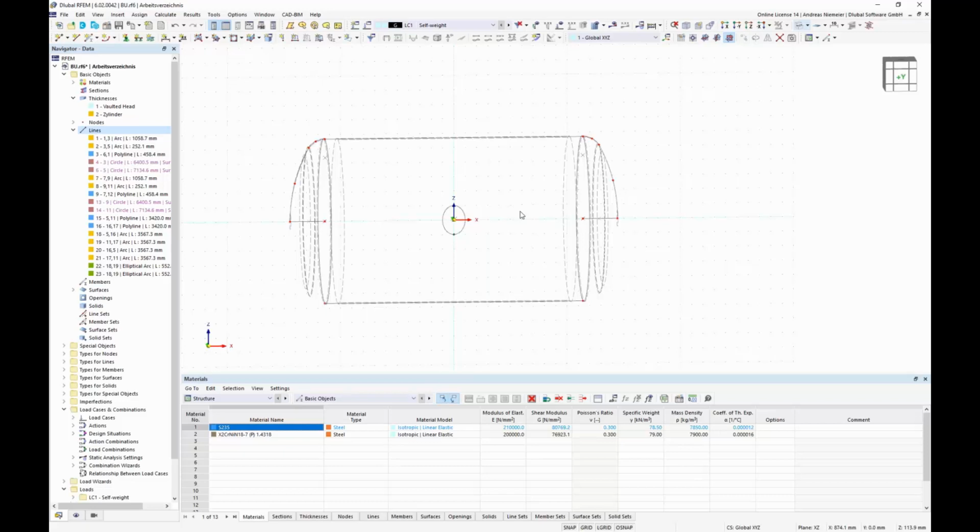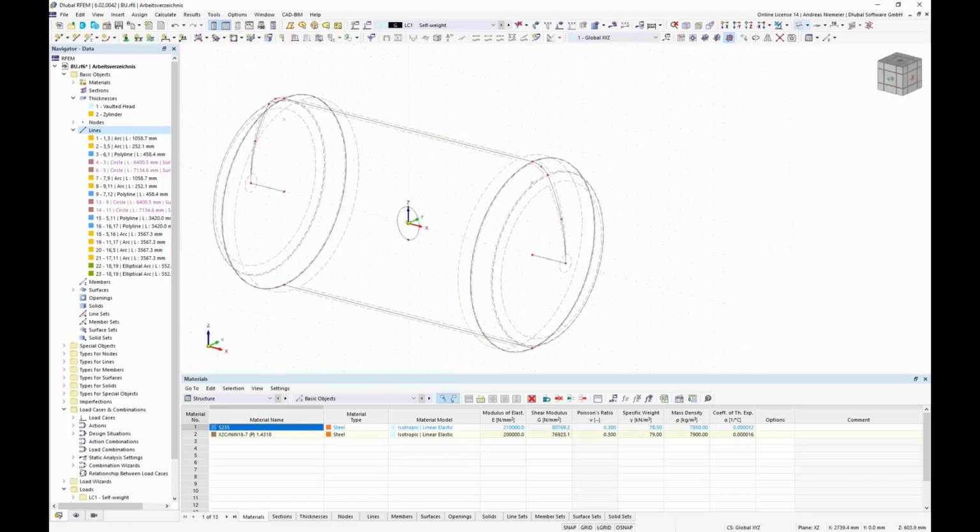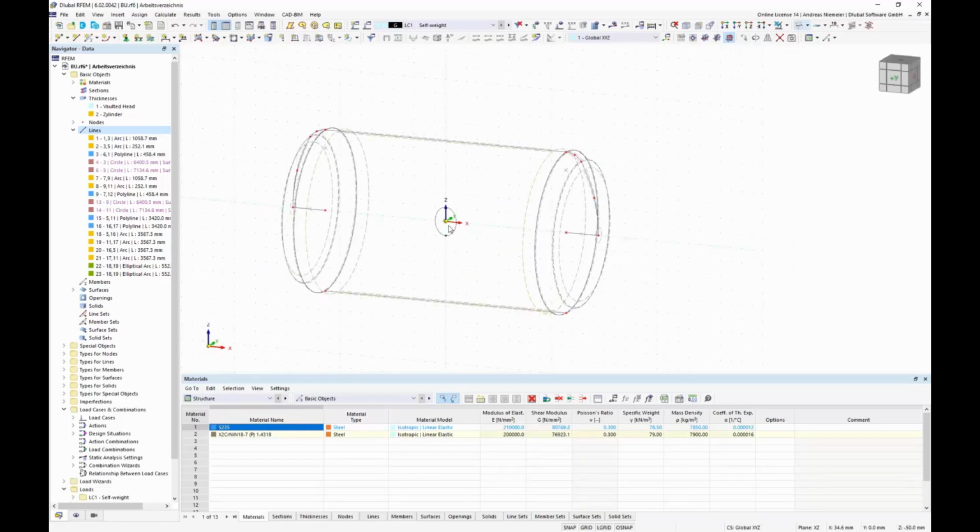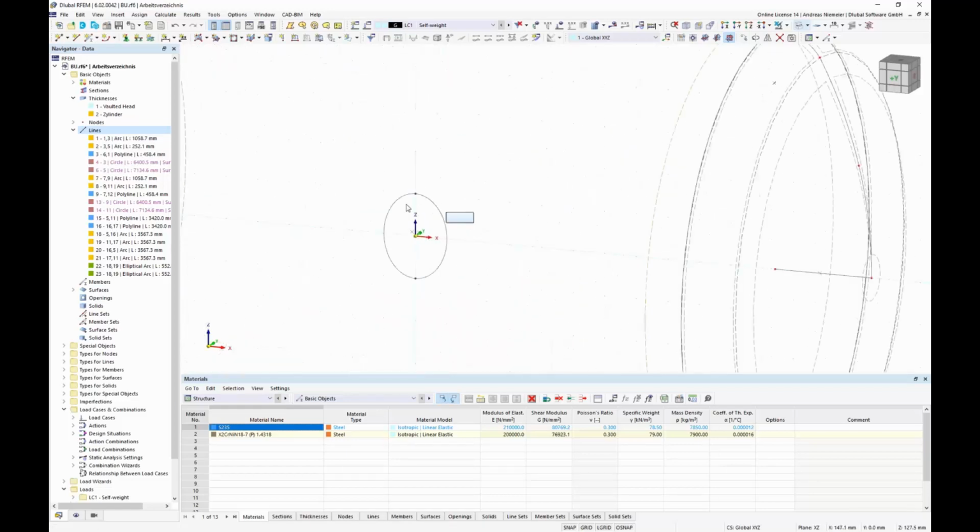Now we can use this geometry for cutting out the hole of the curved plane, but before, I want to think about it. When we cut out the hole of this vessel, we have a hole here and it's pretty slender, so we want to stiffen it. So we want to create a stiffener around the hole, and the stiffener should have a height of 150 millimeters and a thickness of 20 millimeters. So I use these 2 lines to create this stiffener first.